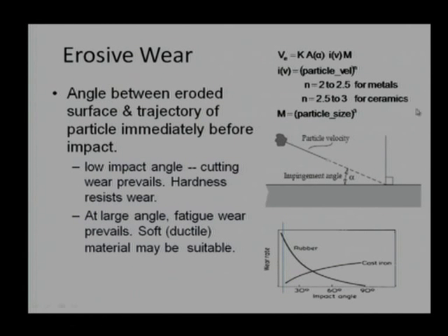And this is what it shows: if the impact angle is 0, I am talking about an absolute 0, then there will not be any wear rate. That is why this initial curve does not show anything. The particle is not touching the surface, not impacting it, not coming in contact at all, right. So, wear rate will be 0, and it does not matter which material we choose.